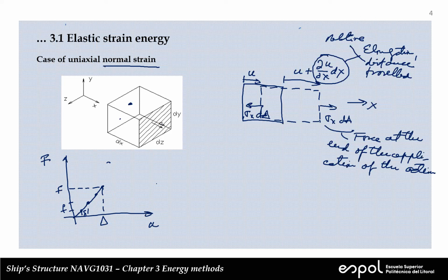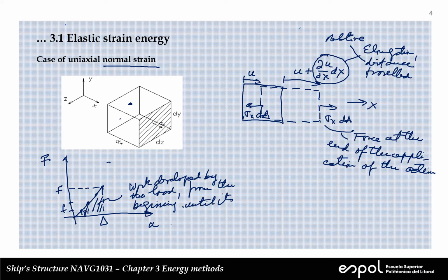So the final displacement is du dx times dx, and the force is simply sigma x dA. But you can see immediately that the area here is the work developed by the force, the load, from the beginning till its full value.